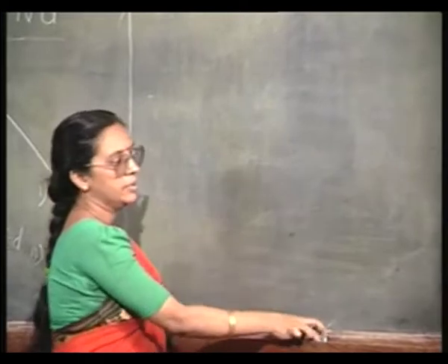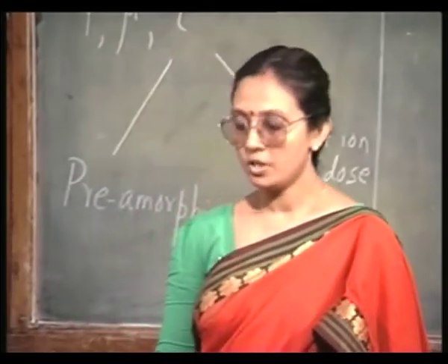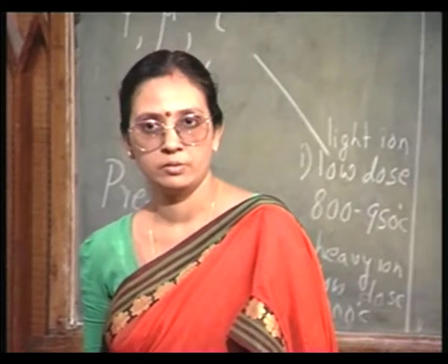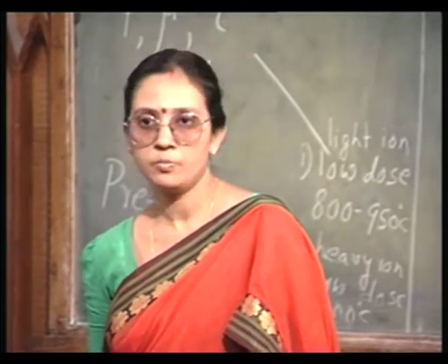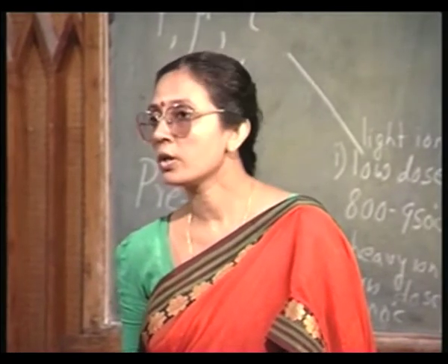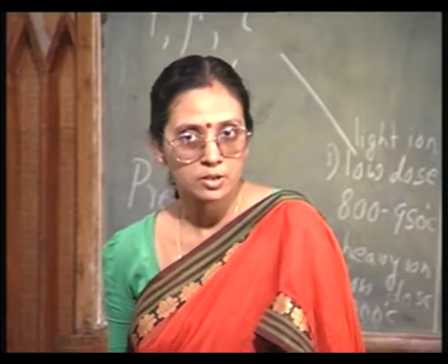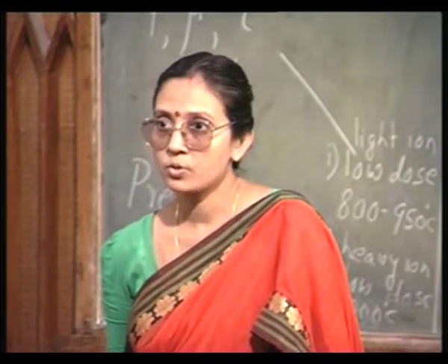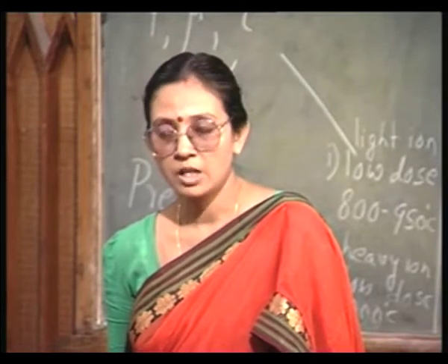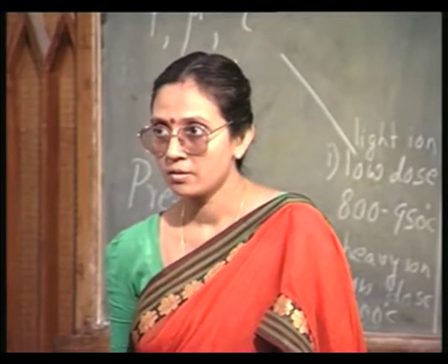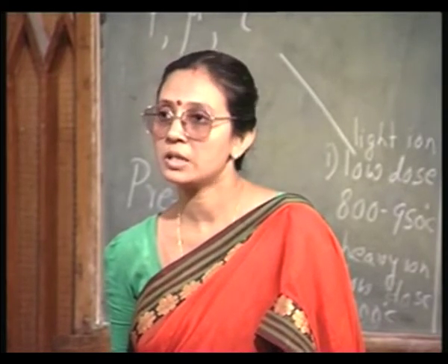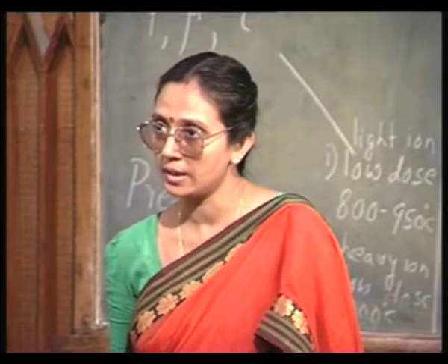Let us think about the two profiles. During implantation, the profile you had is a Gaussian profile. You have a Gaussian ion implanted profile. Now, when you are carrying out the annealing, you are not supplying any extra dopant material. So it is actually a constant total impurity case, analogous to drive-in. I am not supplying any extra impurity; whatever impurity was put inside the semiconductor is still remaining there.